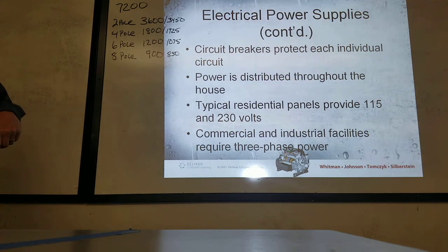According to the National Electrical Code and the Electrical Union, circuit breakers are there to protect what? Individual circuits? Humans? No, there's no circuits if there's nothing plugged in. Those circuit breakers in your house are there to protect the wiring. That's it.